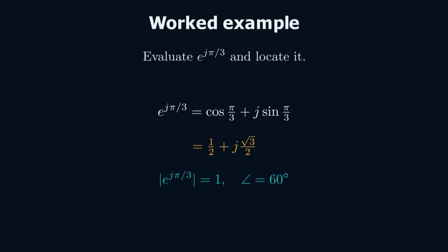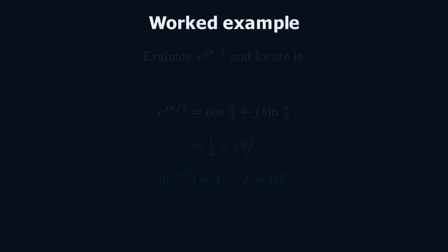You just turned. Everything else in signals and systems, convolution, Fourier, Laplace, sampling, the Z-transform is built on this one rotating arrow. The number to remember from this episode, 90 degrees. That is what multiplying by j really does.